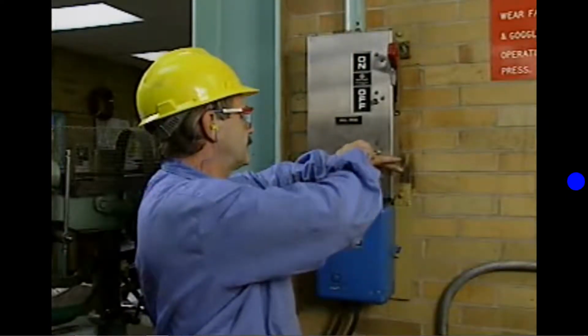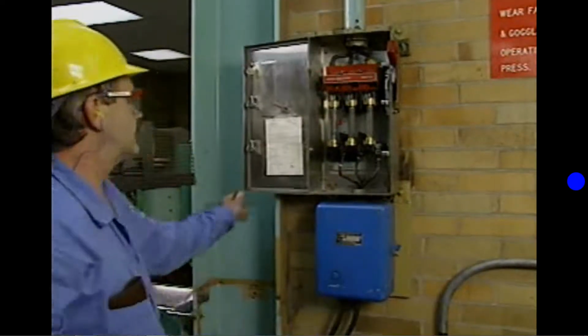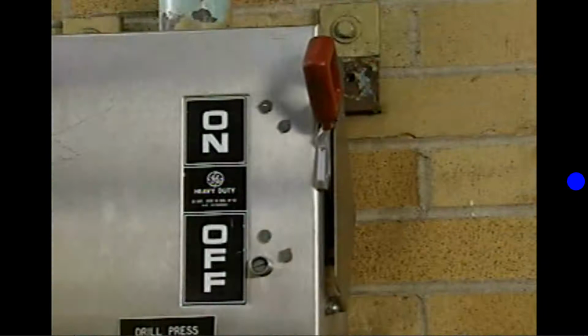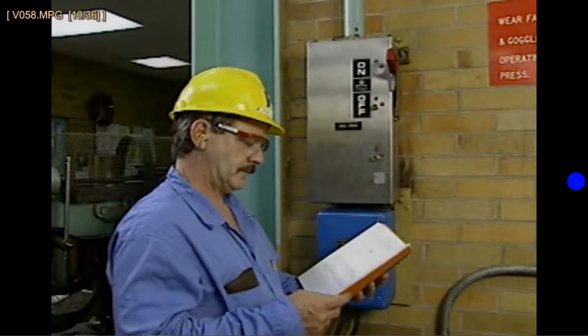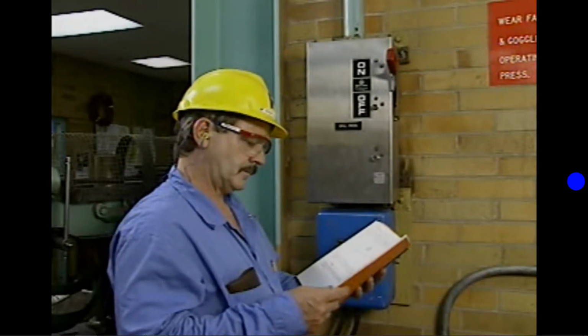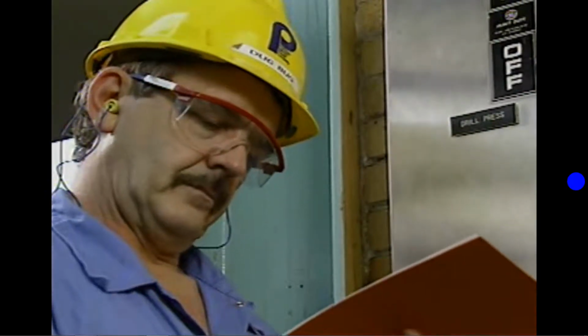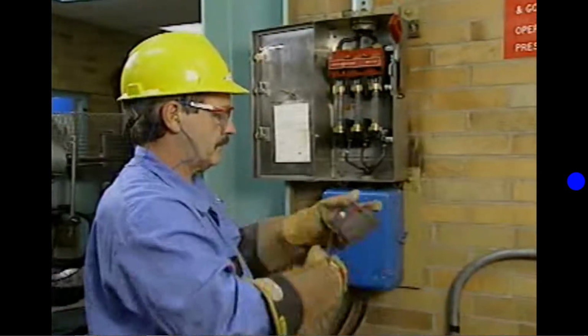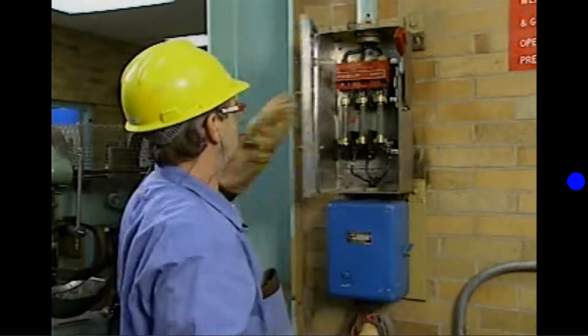The top interlock must also be turned to open the safety switch when the switch is closed or in the on position. For example, you may need to open a safety switch's door to take voltage readings while the switch is in the on or closed position. Before you override any interlock, you need to check your facility's policies and procedures and make sure you follow all applicable safety procedures. After all necessary tests have been completed, this safety switch's interlocks are reset by closing the enclosure door firmly.